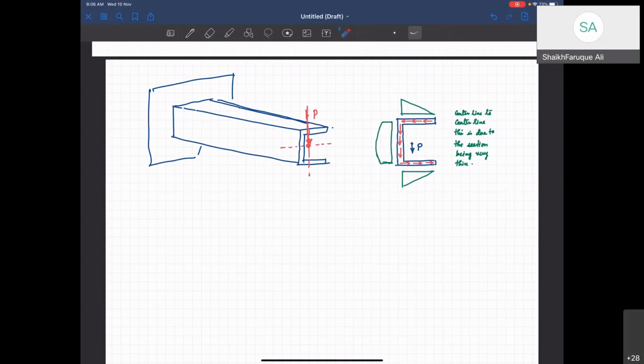All right, so this is how it looks, right? The shear stress or the shear flow will look like this, and we know how to calculate this point, the maximum and the minimum stresses here. The maximum stress here, the maximum stress here. This is called shear flow. It's not stress. Shear flow has a different unit to shear stress, okay?